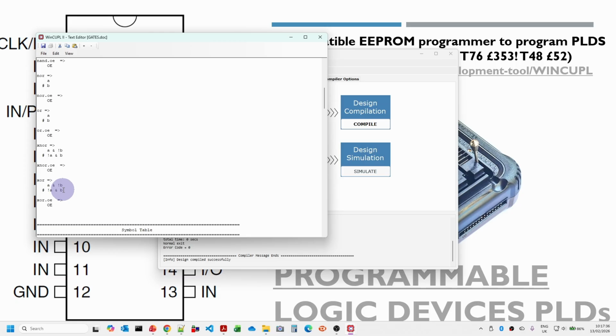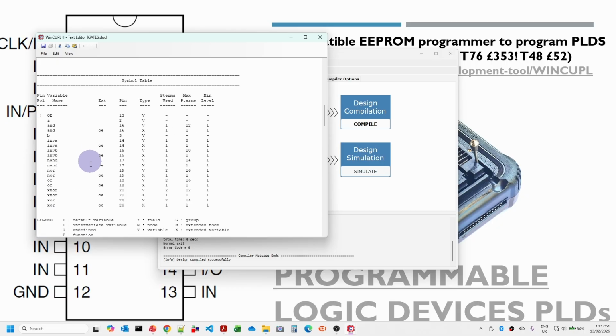And what we'll see when we come to one of the slides later is that this is exactly how exclusive OR and exclusive NOR can be implemented using individual logic gates. And the symbol table here is also quite useful in that if you see one of these labels here and there's no pin number associated with it, it is likely that you've got a typo.